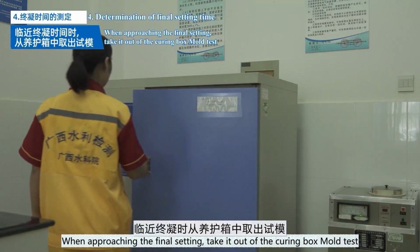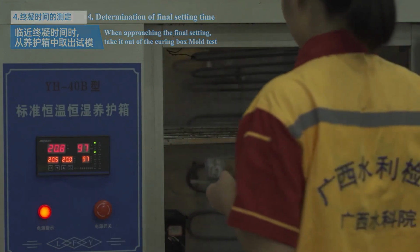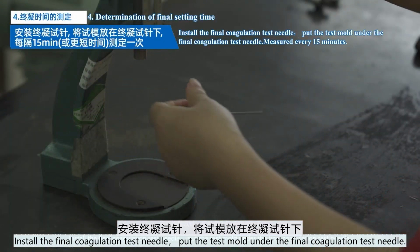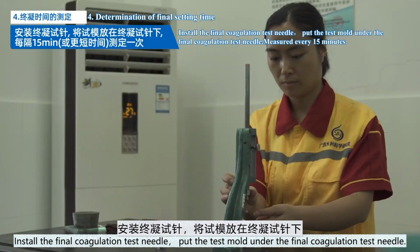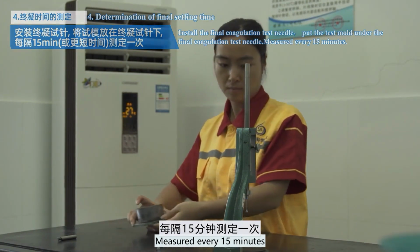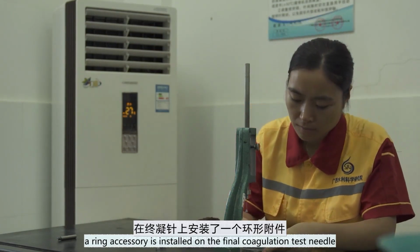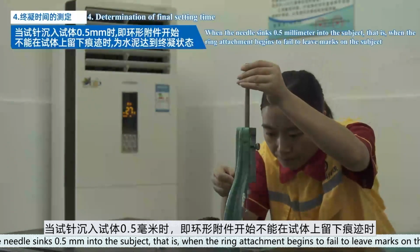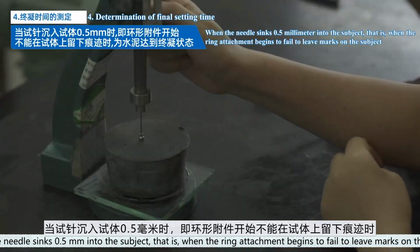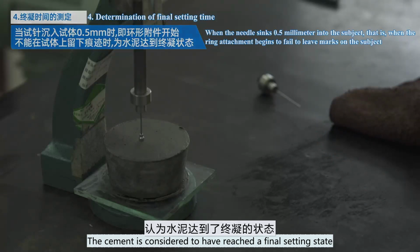When approaching the final setting, take the test mold out of the curing box. Install the final setting test needle and put the test mold under it. Measure every 15 minutes. In order to accurately observe the situation of the test needle, a ring attachment is installed on the final setting test needle. When the needle sinks only 0.5 mm into the specimen, that is, when the ring attachment begins to fail to leave marks on the specimen, the cement is considered to have reached the final setting state.